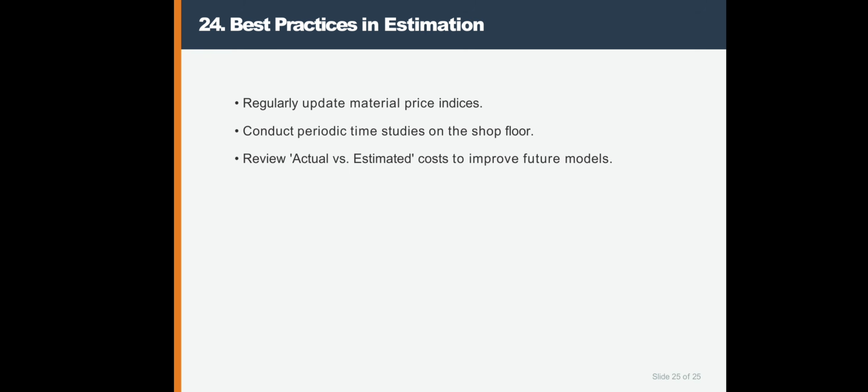The indirect material cost is the cost of materials which are essentially needed in various shops for helping the direct materials to convert into finished product. So what is meant by indirect material? The indirect material is the one which cannot be traced as a part of the product. It is the material required for maintaining and operating the plant and equipment but cannot be a part of the product. Examples of indirect materials are grease, lubricating oil used to lubricate the equipment, coolants used to cool the job and the tool, cotton waste, kerosene, etc.